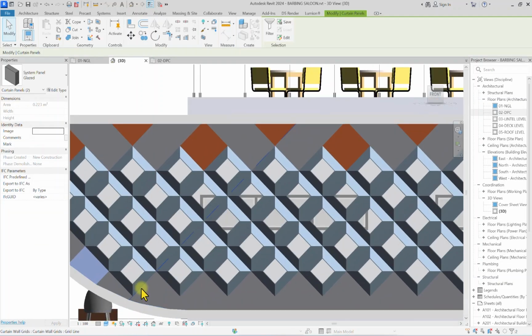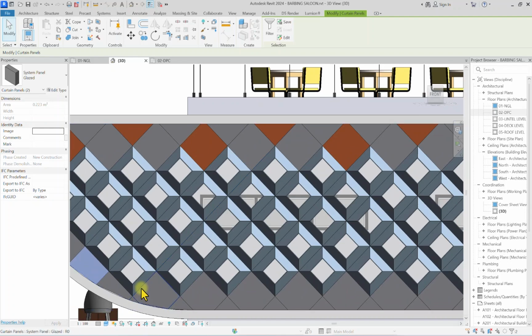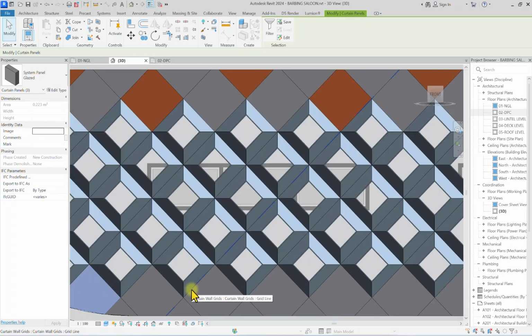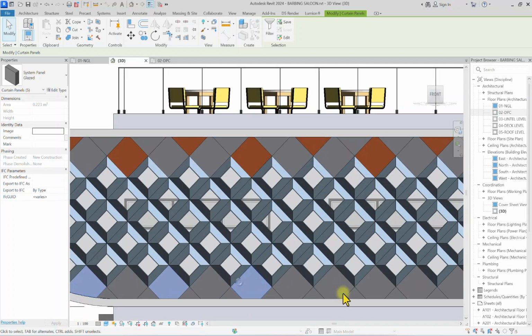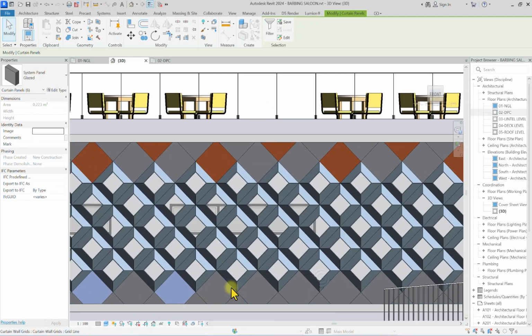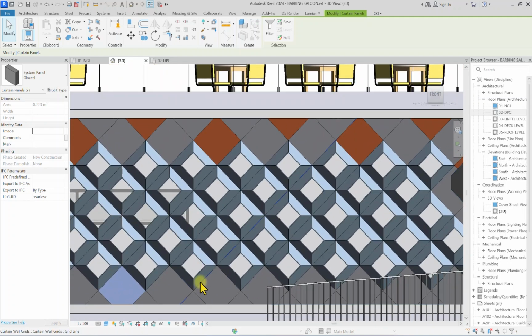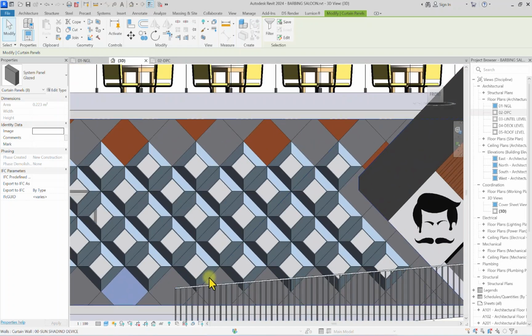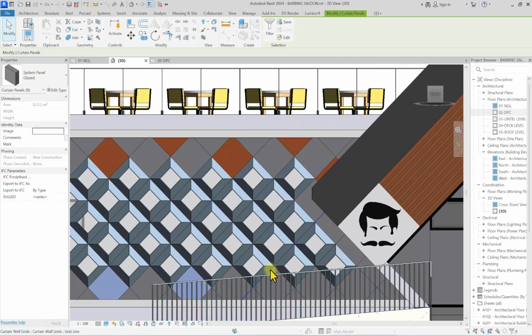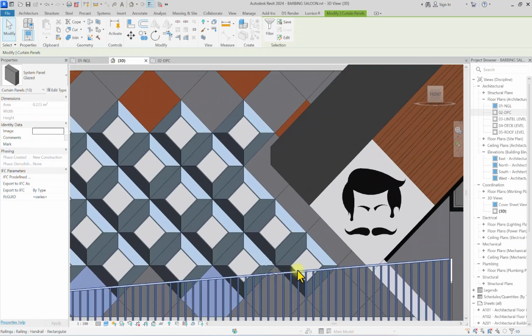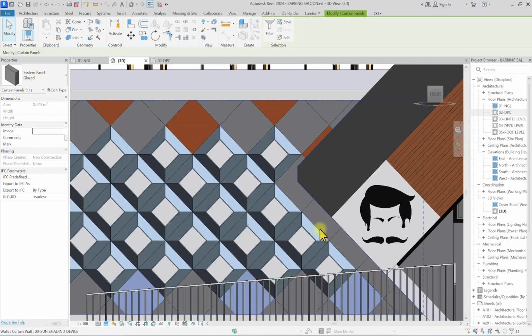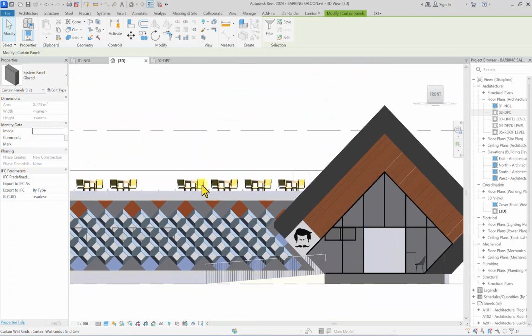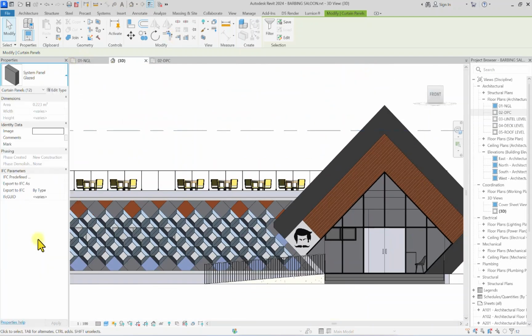Of course, this may not be perfect as how we envisioned it, but as a designer and a BIM modeler, it's always good to be able to adapt and manage with the tools you have at your disposal. So I'm going to select all these ones in an alternating fashion. Yeah, this railing is obstructing, but it's not a problem. We're going to zoom in, click on tab, select Control. So I'm going to click on this drop down, and change it to gold panels.